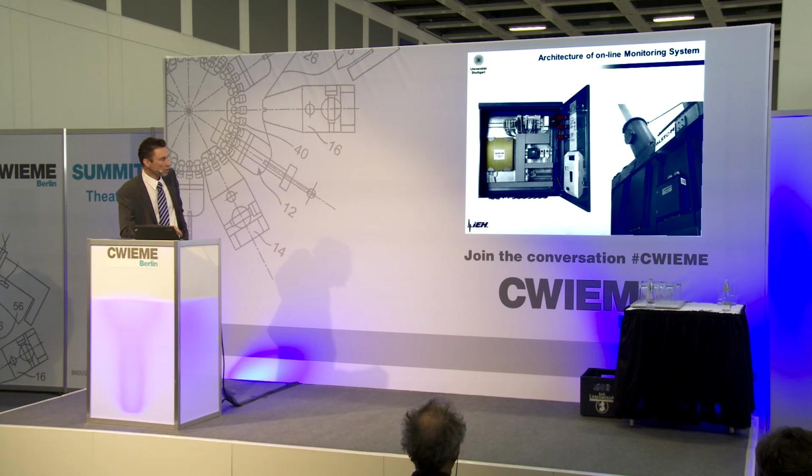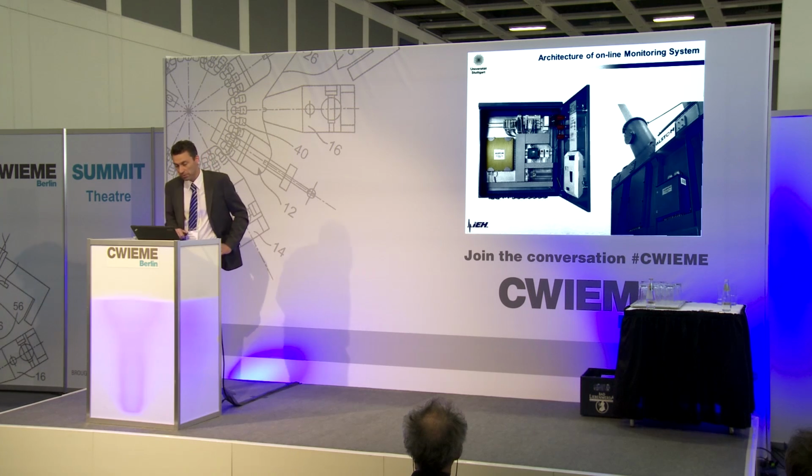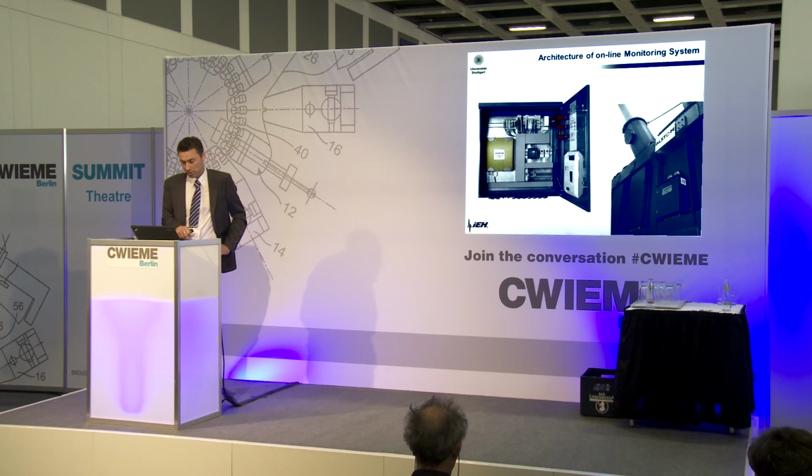This is the inner side of such a cubicle. So you have here these bus terminals to digitize the signals, and then just one field bus cable. In this case, the PC is installed also in the cubicle, so not in a room in the substation. Modern industrial PCs are really able to be installed in such a cubicle, which is installed directly at the tank wall of the transformer.